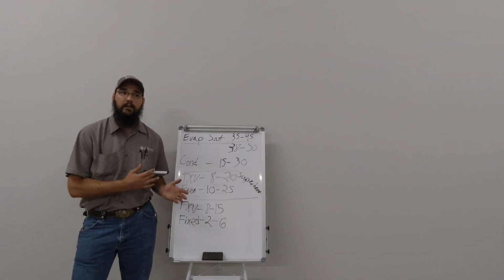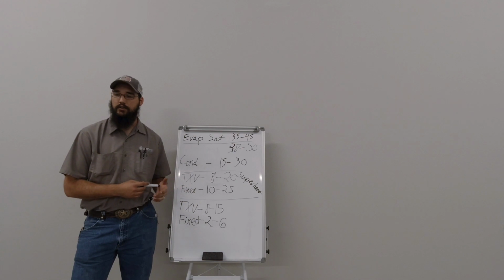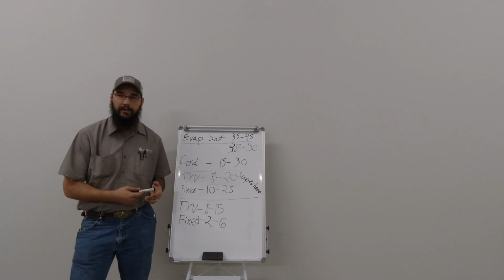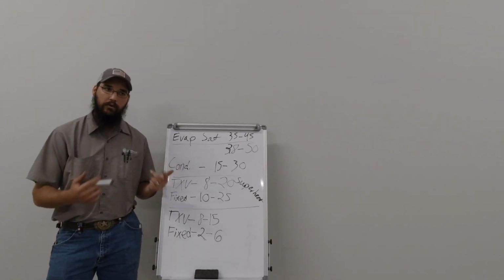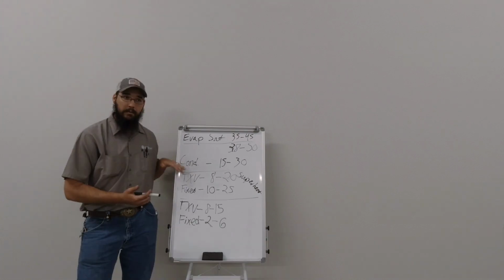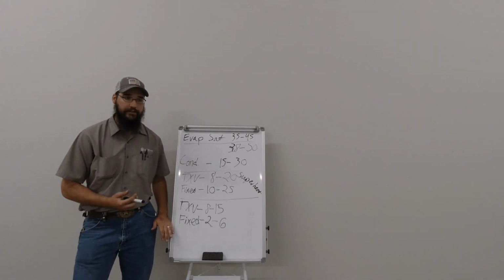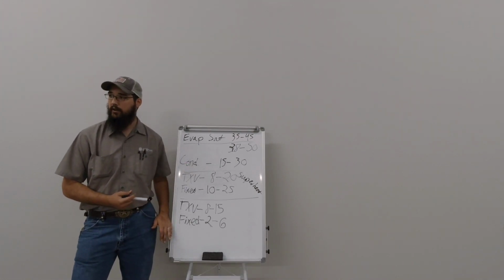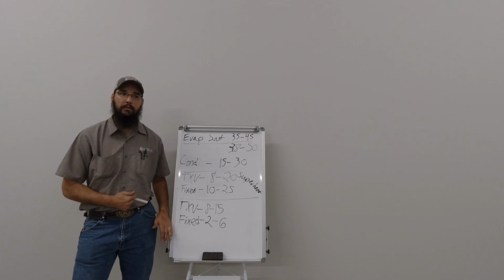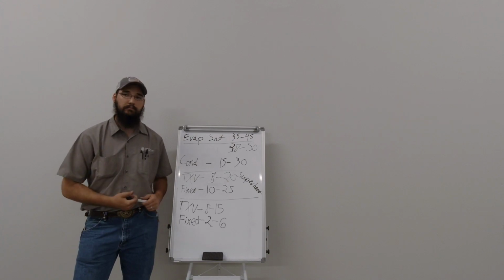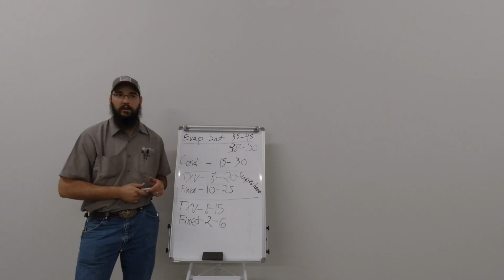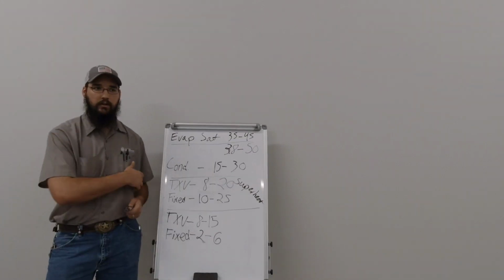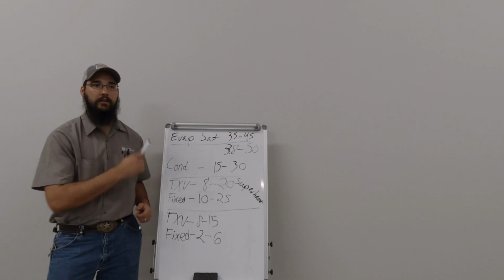You're still charging via the superheat, right? Just like with a TXV, you're technically still charging via the subcool. But in both cases, all the readings still fully apply. Keep in mind, all of this is just very general, everyday stuff. There is a ton of equipment out there that's going to operate outside of these parameters, and it be on purpose. VRVs are an example of that. Very high efficiency systems are an example of that. Chillers are a whole other ball game. This doesn't mean anything to a chiller.